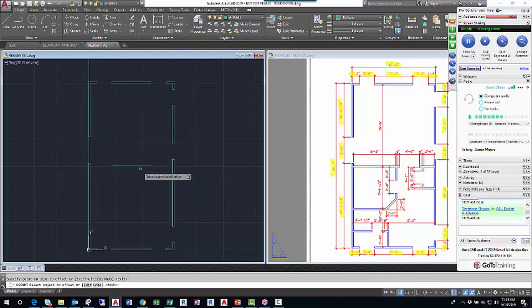So that line doesn't really look like the line in the markup, but when I get done with it, it will. Now, all my walls are 3.5 inches thick, so I'm going to offset this line down 3.5. So I'll restart offset, 3.5, enter. Left click that horizontal line, move down the screen and left click.